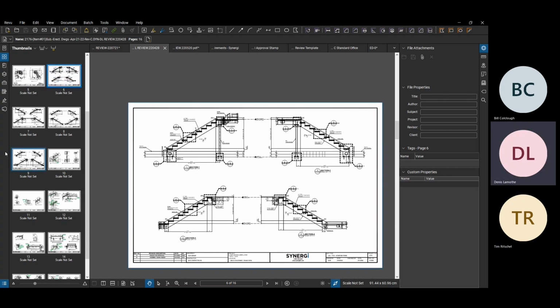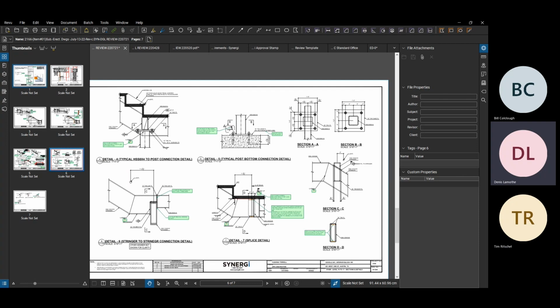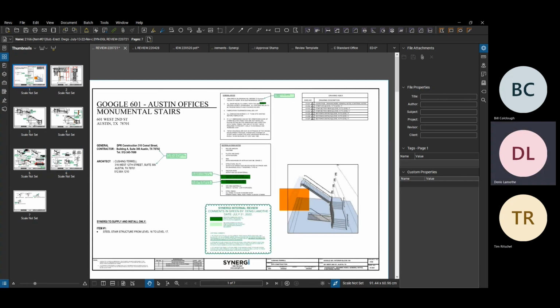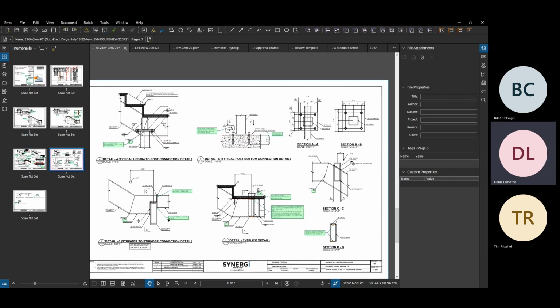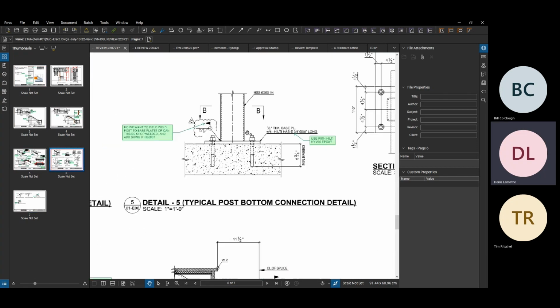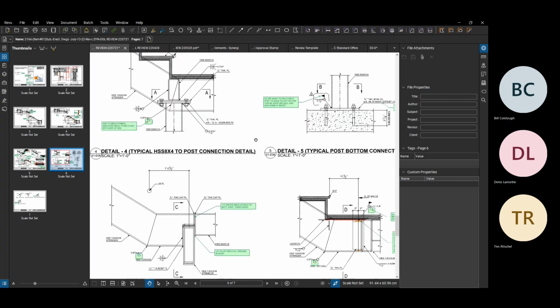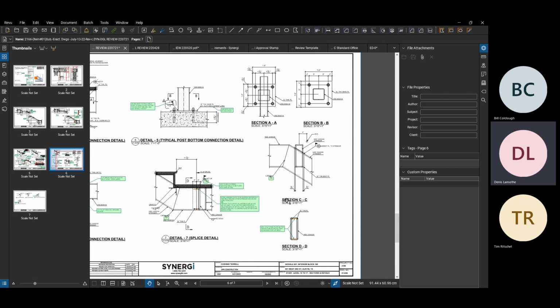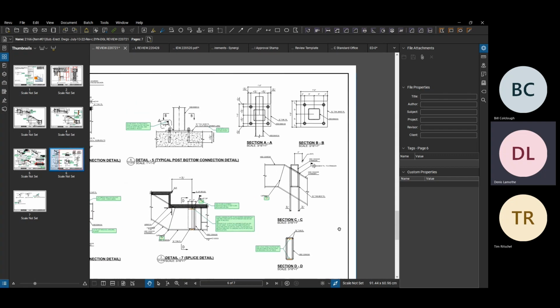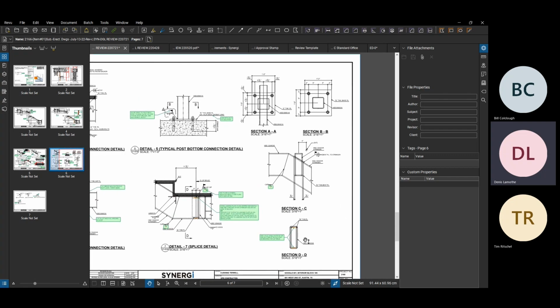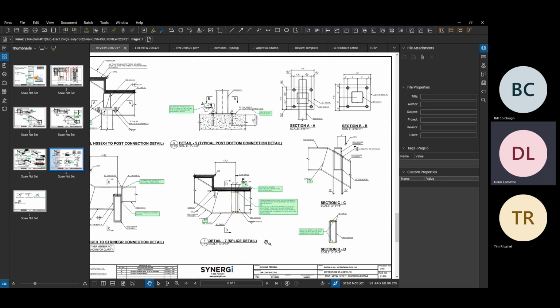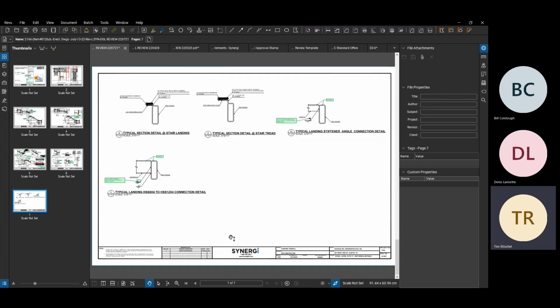Yeah, it's somewhere. So we'll check splice joints. We'll check, yeah, we talked about material finishes and notes on the cover sheet. Any specifics that the engineer may want us to show in terms of connections, maybe to the floor slab, whether it's for a post or the stair stringer. Make sure that the drawings match what the engineer needs. The engineer won't stamp our drawings unless we match what they've sketched and what they've approved and calculated.